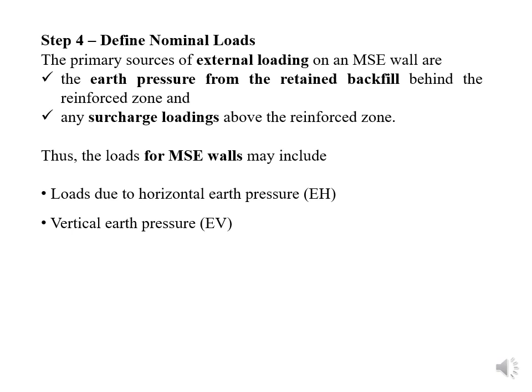If the height is more, vertical stress is also going to work on your retaining wall, and horizontal stress too. Live load surcharge, if any, for example a vehicle moving on top of the retaining wall, you have to consider.